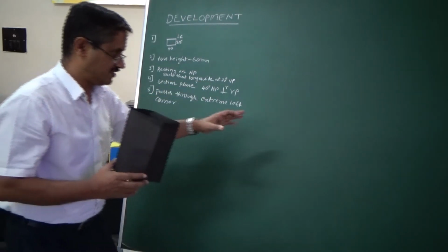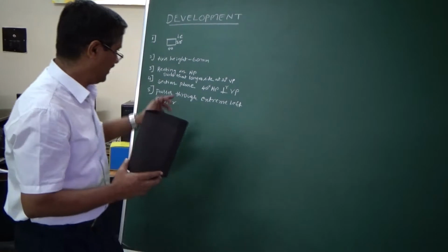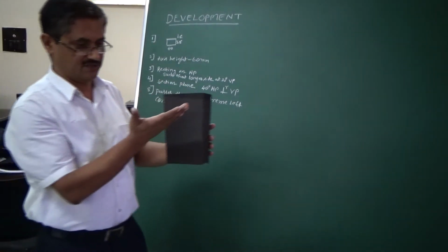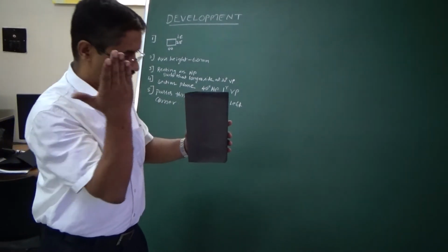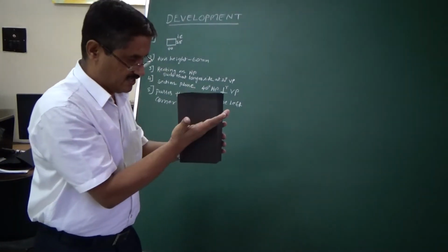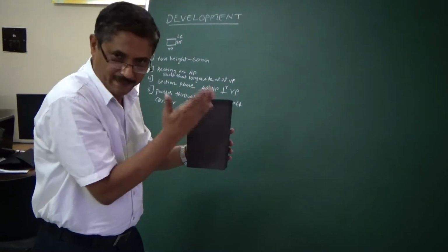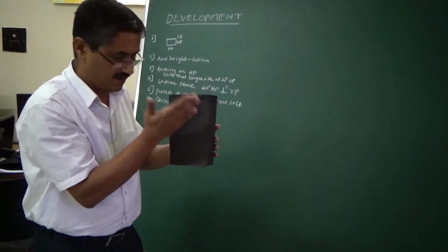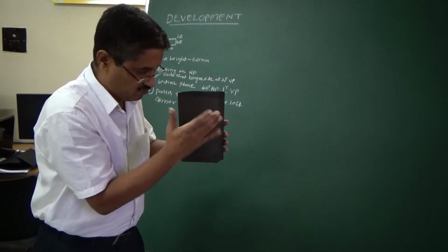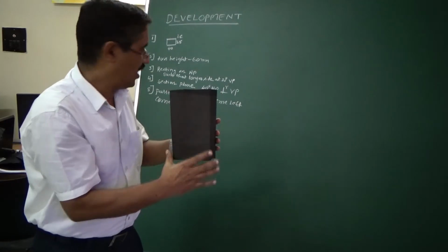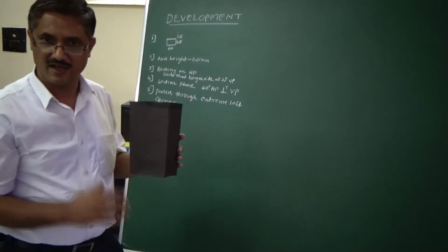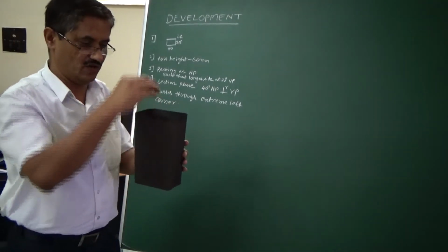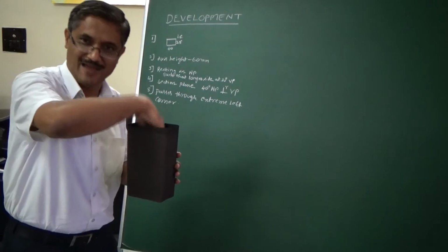Once you construct stage 1 for this, then in point number 4, we take a section plane and cut this solid. When we cut this solid, it becomes 2 pieces. The one piece, the below one, can be retained, or the top one can be retained. However, for the truncated portion that remains, you have to develop that portion of the solid. So now we are taking the surfaces only. It is not a solid, okay? It will be hollow inside.